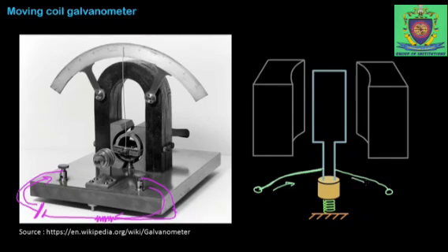Positive to negative. Now in the presence of the magnetic field, the current is flowing like this, and due to that a torque will be experienced. So the torque or the force is experienced and it creates a rotatory motion. So in the presence of the magnetic field and the current, it experiences the torque, where you can see with the arrow mark. Okay, when it experiences the torque, see here it is connected to your spring. Okay, it is connected to the spring here. So when the rotation is happening, your spring also will start to move. See, for example, the rotation is happening in this way.